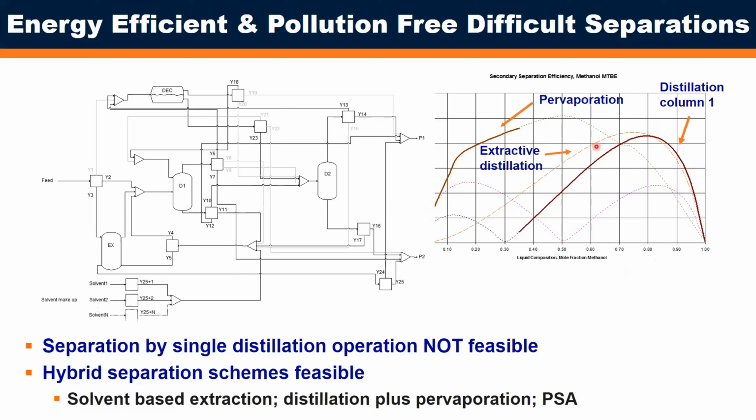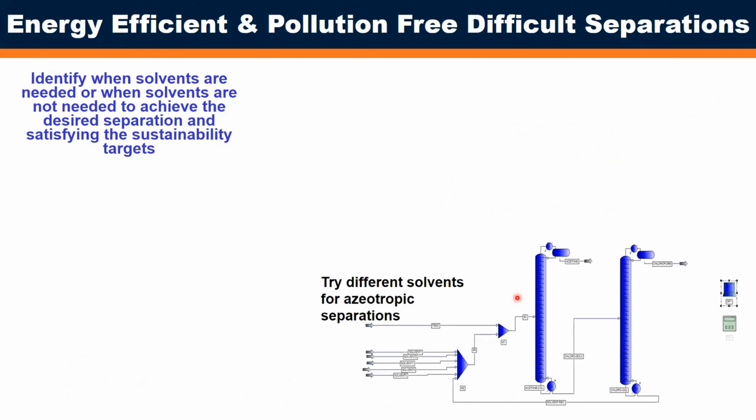And we even have extractive distillation in the middle here, where ideally we could make a system that maximizes driving force to a certain point and then uses the next one for the parts where that technology has the highest driving force. That way we're maximizing the utilization of the driving force and hence minimizing the energy requirements.